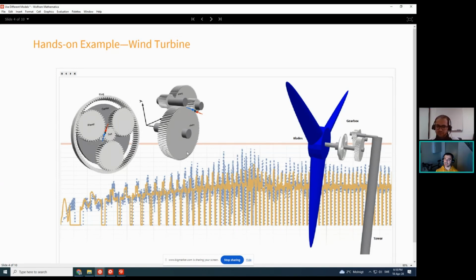Here we are looking at a blade where we harvest the wind energy from, and that blade, let's say, rotates at really slow RPM, maybe 25 RPM. But to generate energy, we require higher RPMs, let's say maybe 2000 RPM. So we need to somehow increase the speed of the shaft going into the generator. That is why we use a gearbox.